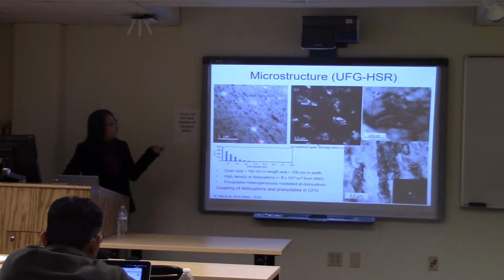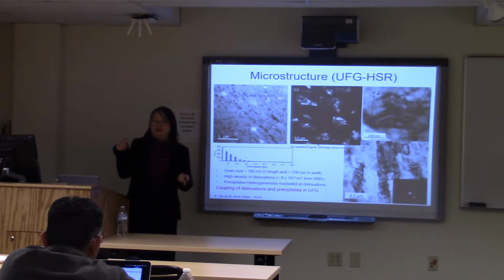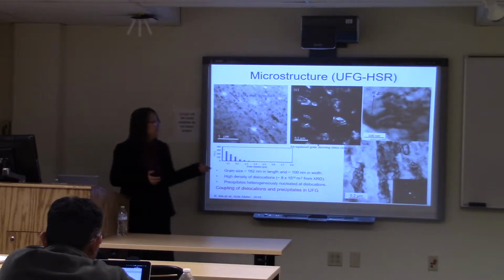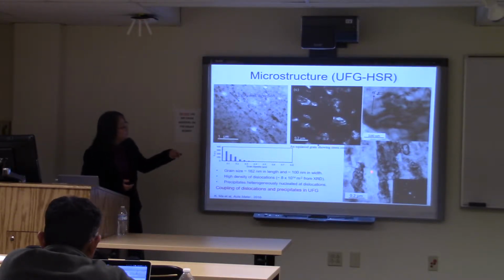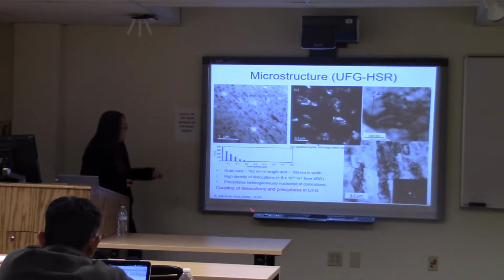So again, we cannot avoid studying the microstructure. First, I want to confirm what I want. I did get a coupling of dislocations and precipitates using this processing. So this is the extruded condition, and you see a lot of deformation and dislocations in here associated with your precipitates.